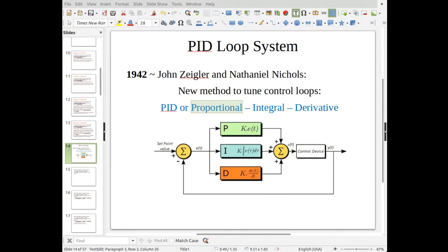And delta t, you could actually just use the scan. The problem is that we don't really know what the scan time is, and the scan time will change based on how much code you have. So what we do is build a special timer in there so we understand what delta t is. But the problem with that is that it's adding extra delay. We might make delta t, say, 5 milliseconds, and that's an extra delay built into the system, which can drive the system into that instability we talked about.